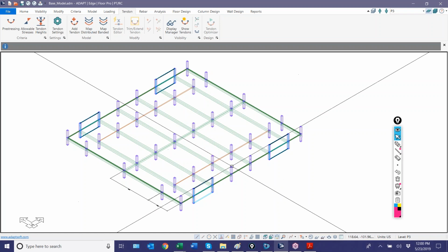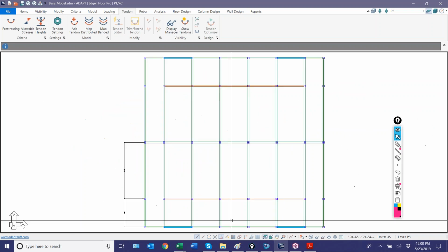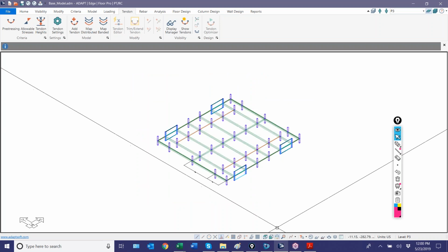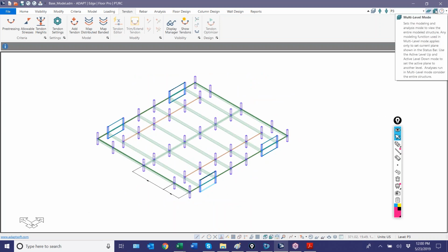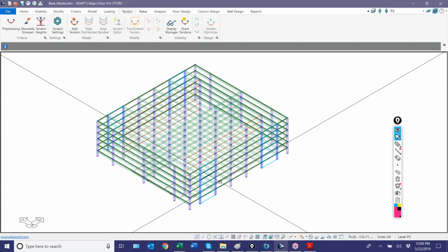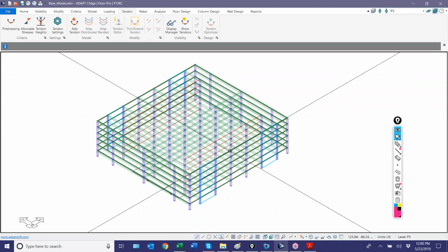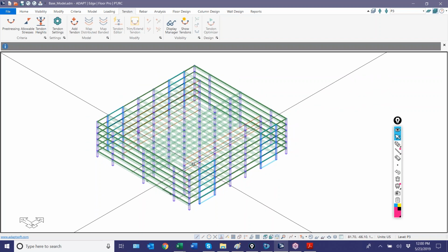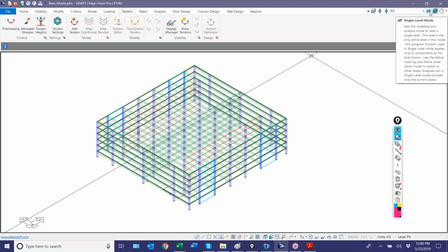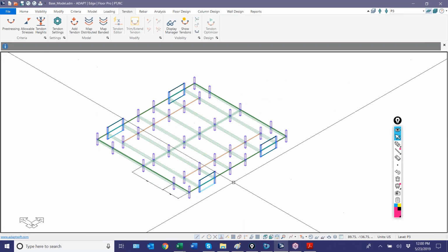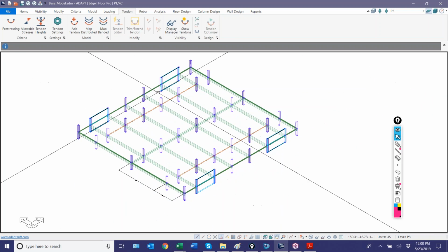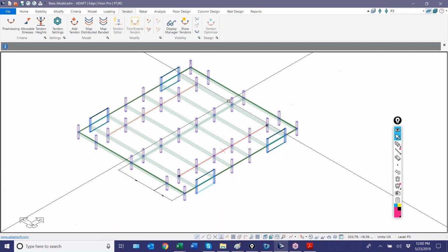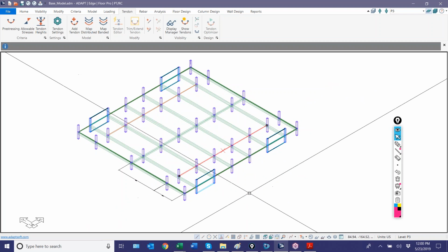And last week we ended by adding support lines; we essentially imported the model from Revit. We're looking at a single level of that model, and we idealize this model as flat slabs, where in reality there are ramps that connect the slabs for this particular parking structure. But for the gravity only design, we're going to look at this in single level mode, in isolation, for level 3. And we had loaded the structure. We had modeled some openings here that disconnect the slabs, where you have the ramping on the outsides and then the flat portion in the interior.